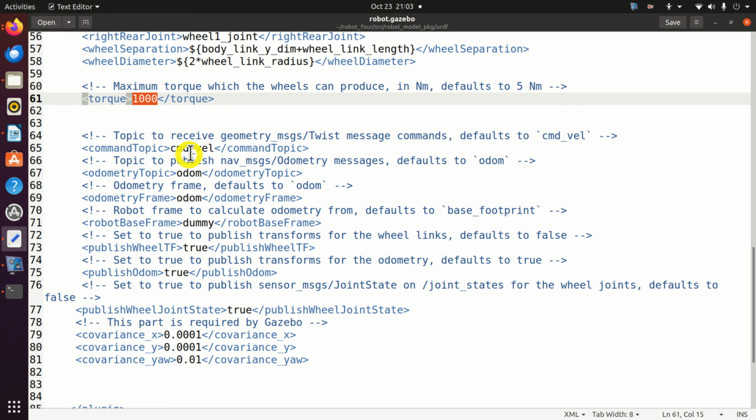We will send the control commands by using the Twist ROS data structure. That is, we will be using this standard cmd_vel topic. This cmd_vel topic will be used to communicate velocities and angular velocity of our robot. These velocities will be sent actually to the controller, and the controller will implement them. That is, the controller will move the wheels such that the desired velocity is achieved.